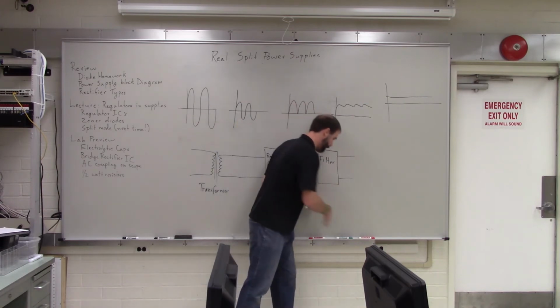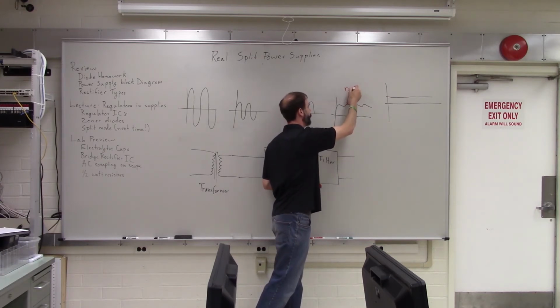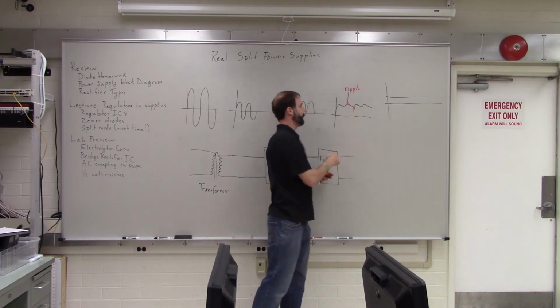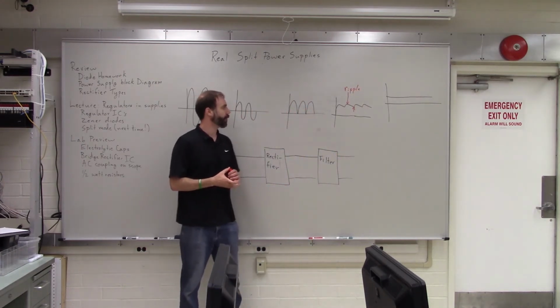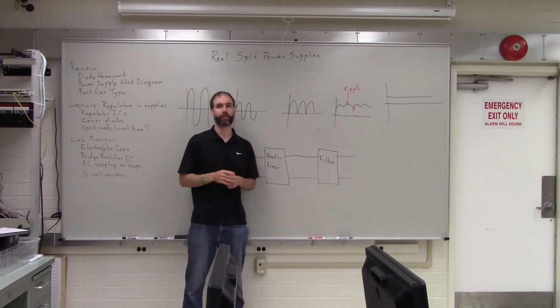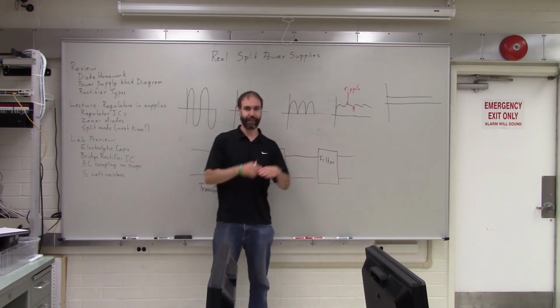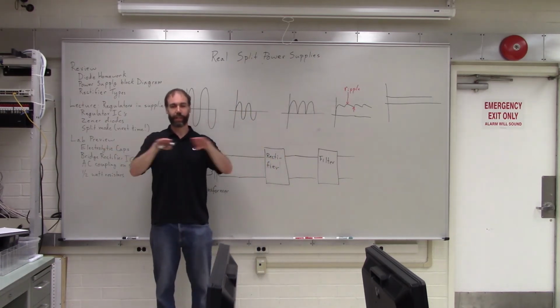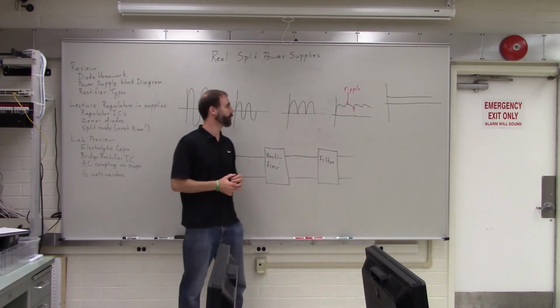And what did we call this small change in the voltage from the top to the bottom here? Yeah, that was our ripple voltage, because it looks kind of like ripples on water. And was it better to have a lot of ripple or a small amount of ripple? Small. Yeah, a small amount, because ideally, you'd have no ripples. A DC signal is perfectly flat, perfectly smooth, so that has no ripples. So the less ripple you get, the better you are.